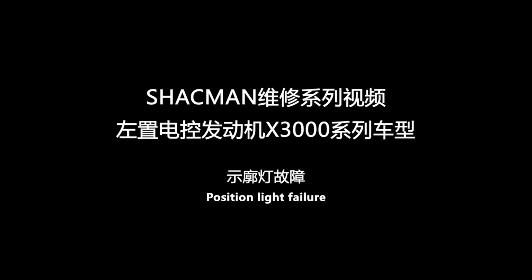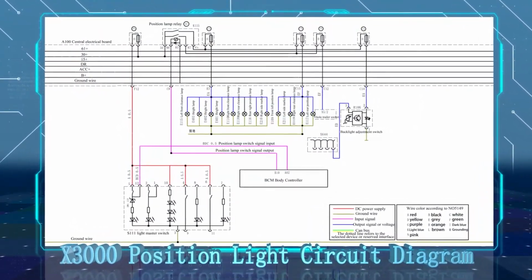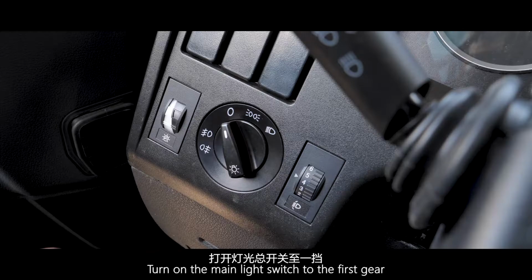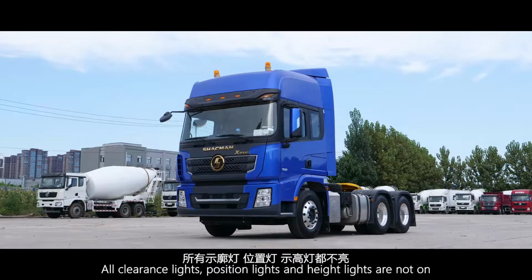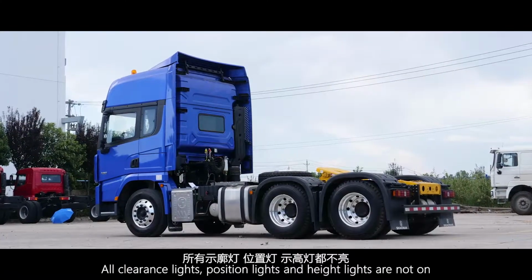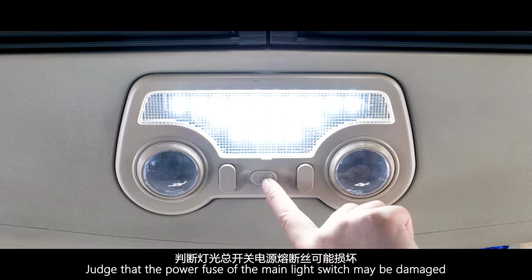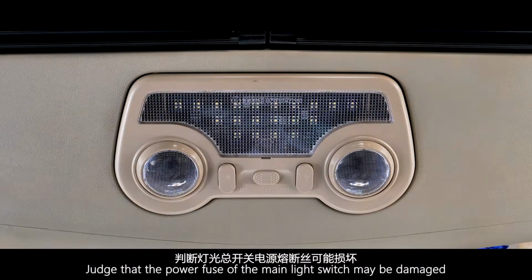Position light failure. Turn on the power supply of the whole vehicle. Turn on the main light switch to the first gear. All clearance lights, position lights, and height lights are not on. The test found that the power supply of 30 was normal. Judge that the power fuse of the main light switch may be damaged.